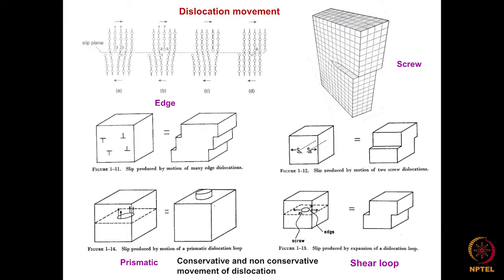This is equivalent to the case which we considered initially, if there are no dislocations, if by one lattice translation vector we have to move one layer over on top of the other, the entire layer has to be moved entirely by one lattice translation vector here like this, correct? That need not be done. Suppose this has to be done, what will be the energy which will be required? It will be very high.